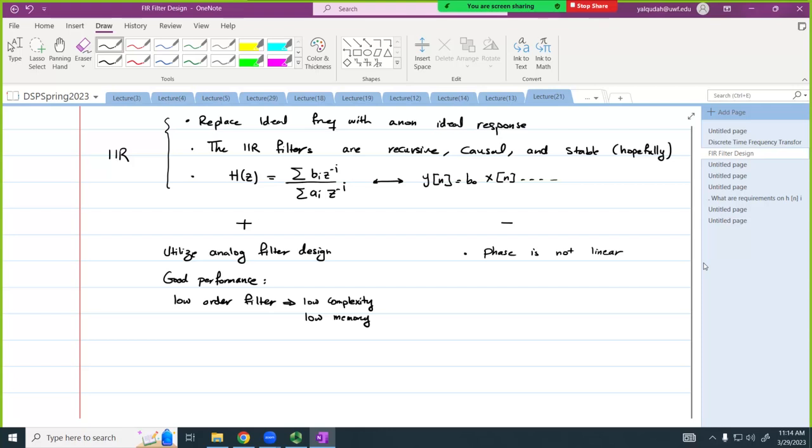That is because in general, for the IIR filter, when we plotted the phase, generated by the freqz of MATLAB, which automatically generates the magnitude and the phase, you've seen the phase was not linear. And we'll see why that is a problem in a minute.